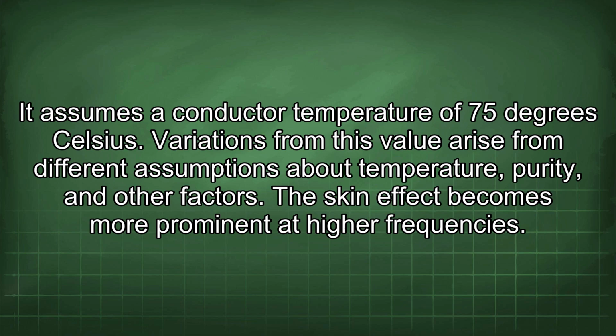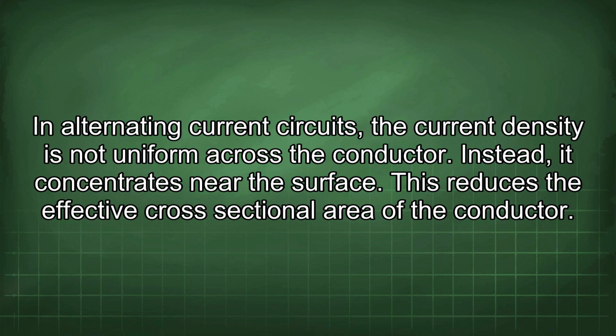The skin effect becomes more prominent at higher frequencies. In alternating current circuits, the current density is not uniform across the conductor. Instead, it concentrates near the surface. This reduces the effective cross-sectional area of the conductor.